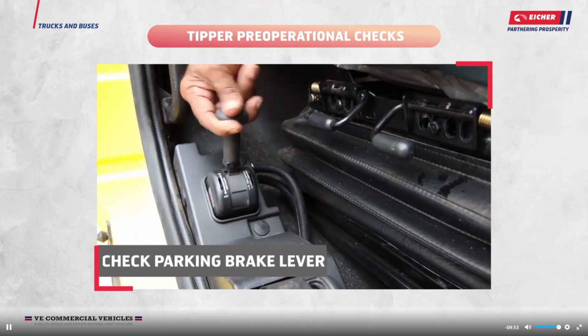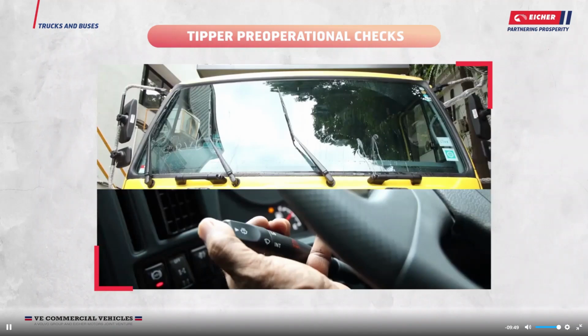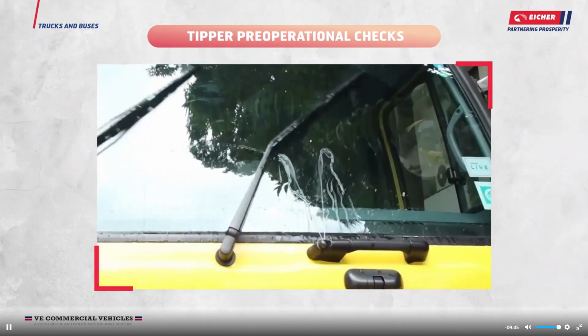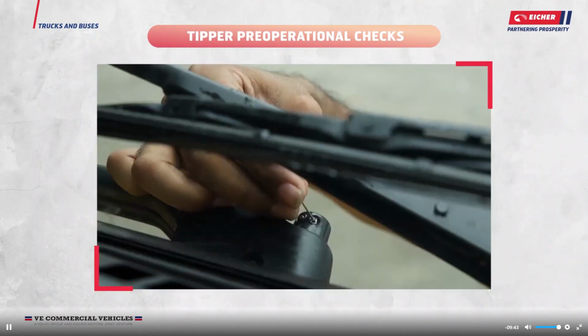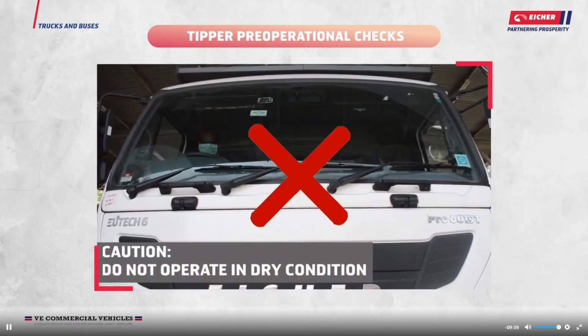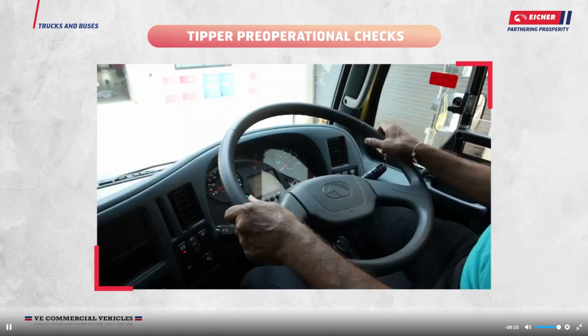Check the parking brake lever function in on and off position. Press the switch and check for windshield washer spray. If the nozzle spray angle is not proper, adjust and clean the nozzle as shown. Caution: do not operate the wipers when the windscreen is dry.